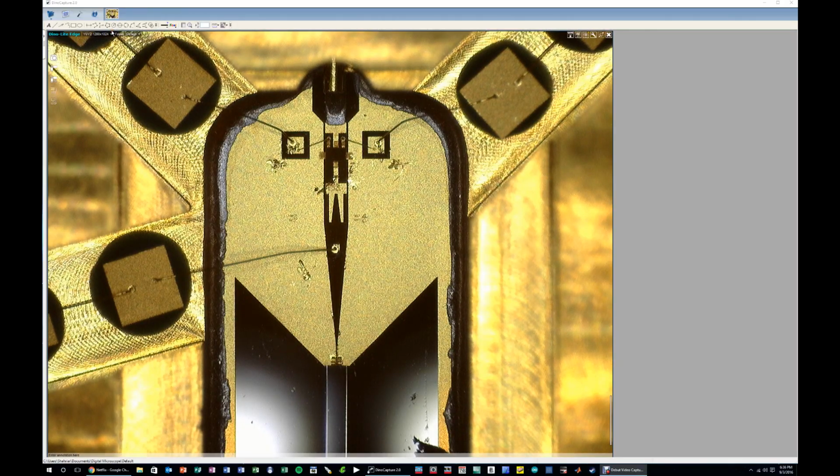And here we have the 50 GHz sampler directly under the microscope, and it looks very similar to the sampler that I showed in the frequency counter video. And the input signal over here, so this signal coming out from this side is the 50 GHz signal, and the signal coming from the bottom over this trace is the step recovery output, which are the very sharp impulses. And there's the sampler detecting module in there, which is most likely a diode simply put there for that purpose. And you can see that it has 2 symmetric outputs, and most likely these are a differential output generated from the 2 halves of the cycles of the diode.